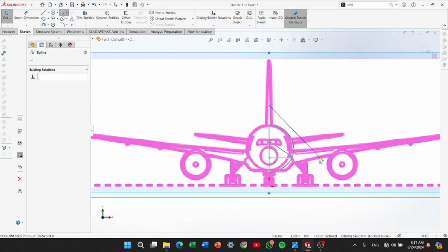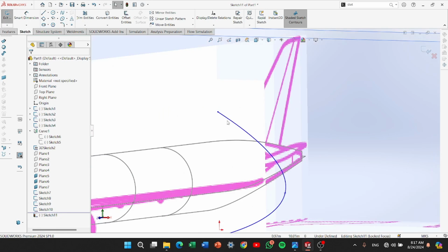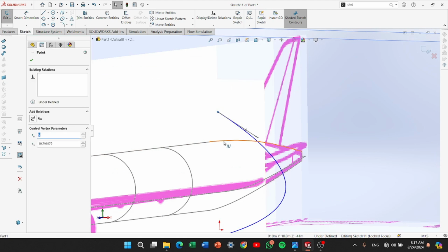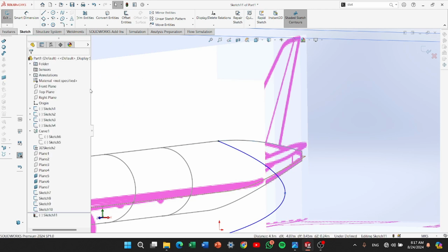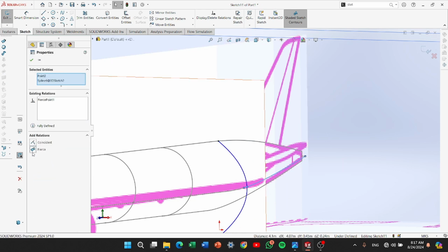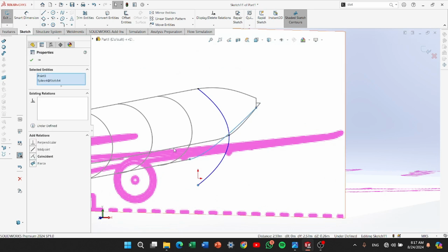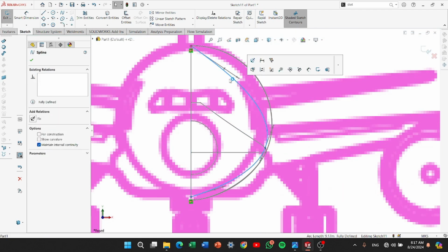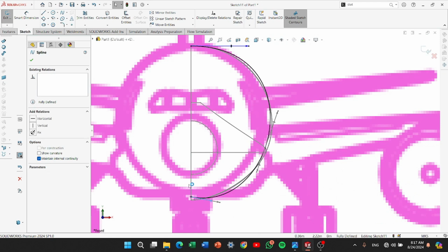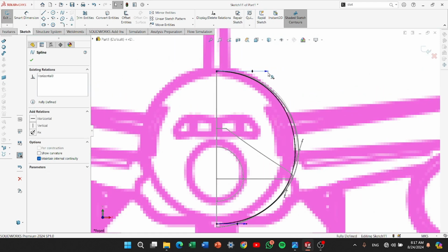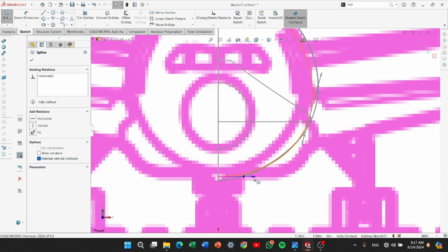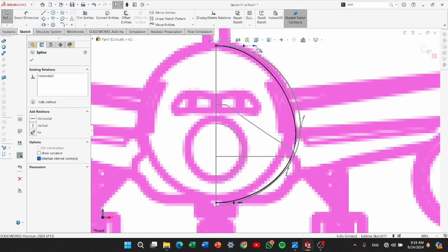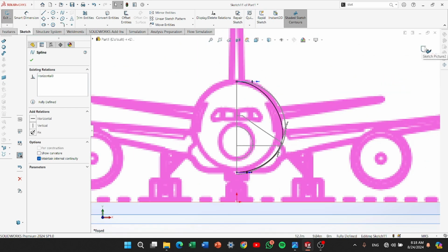So spline. Okay, so it is not in the straight line region. It is in the spline region. So choose this and control choose this. Pairs. Choose this and control choose this. Pairs. Choose this and control choose the bottom spline. Pairs. Okay. No onion shape. As I said again, horizontal and horizontal. Okay. Now I just concentrate a little bit more because it's the back part of the fuselage, so it will be less round. Okay, it's good.